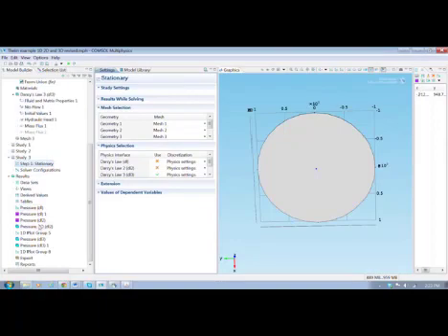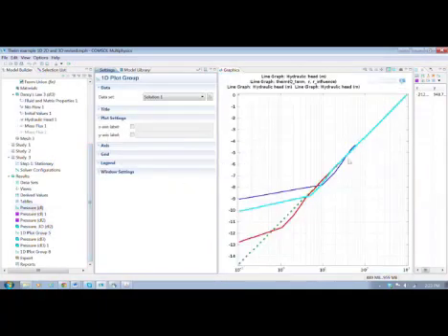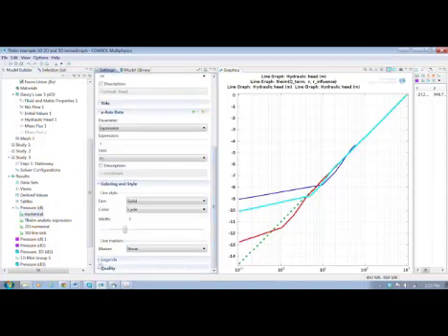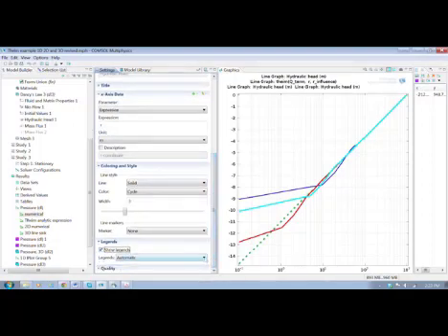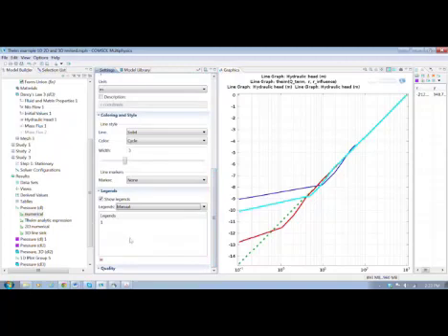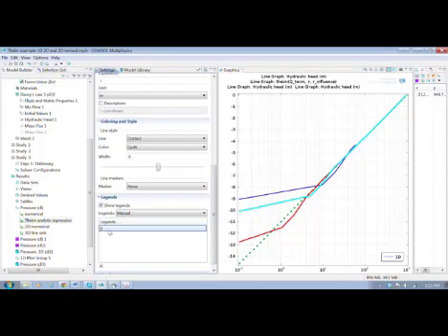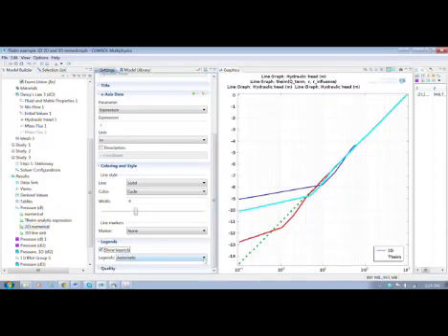And we do that, and if we take a look here at the plot that has all three of the results on it, you can see that it's hard to tell which one it is. So maybe we should go ahead and fix that. So let's put a legend on here in the lower right, and then we can turn the legend on for each one of these. So we have to go and label each one of these legend entries in order to have it show up and say something meaningful. It'll just number them, and it won't really be that useful unless we go in here and label it.